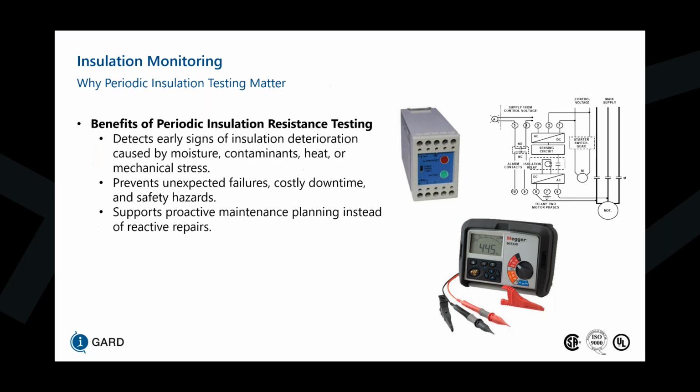In addition to that, there's periodic insulation testing, and that is based on IEEE 43 requirements. This is used to detect early signs of insulation deterioration caused by moisture, contaminants, heat, or mechanical stress. It prevents unexpected failures, costly downtime, and safety hazards, and supports proactive maintenance planning instead of reactive repairs. So by having that continuous monitoring and periodic monitoring, we can actively know when the motor can have a planned maintenance rather than reacting to a motor not starting on site and then trying to figure out what's wrong with the motor at time of failure.